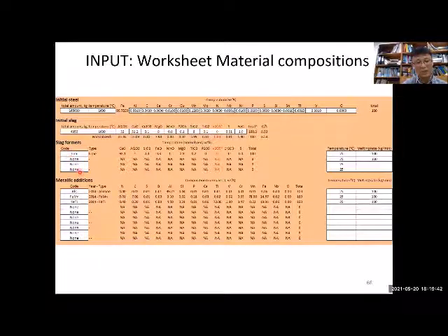And then we are adding different kinds of slag flux. In this case, we are adding only one. It's not pure CaO, it's CaO with all the impurities. And we are adding different kinds of metallic species, up to about 9 different kinds, during the operation. So we provide all those possibilities, including all the impurities, because these minor elements are very important for the final inclusion composition inside of the steel, which is very bad for the steel. And then we consider the initial temperature and the melting rate and temperature of the initial steel and slag to predict the temperature profile of the system.